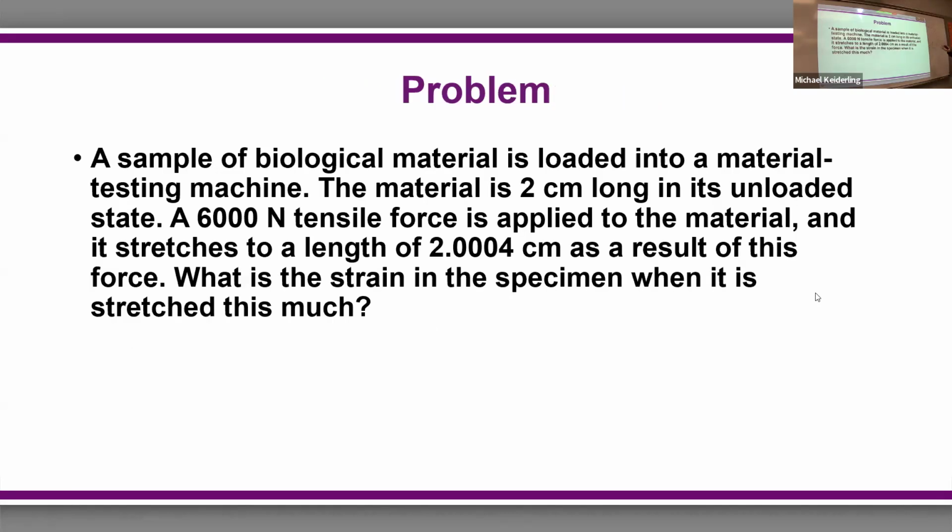So here, if you have a sample of biological material, it's loaded into a material testing machine. The material starts out 2 centimeters long. A 6,000 Newton tensile force is applied to it. And it stretches to a length of 2.00004 centimeters as a result of this force. So what's the strain in this specimen?